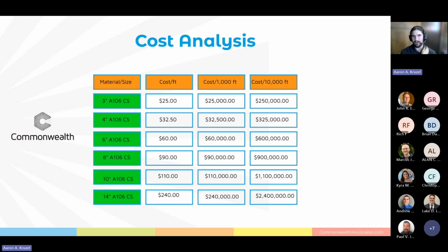You have to calculate all of that, and generally it's not done. It's just done by adding a margin onto the end result. You add a margin to the flow, the pressure and the velocity, and you end up with generally not necessarily oversized pipe, but less optimally sized pipe.